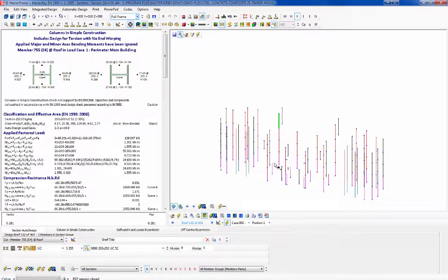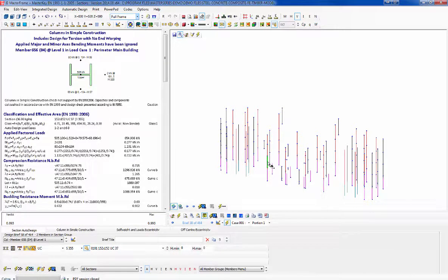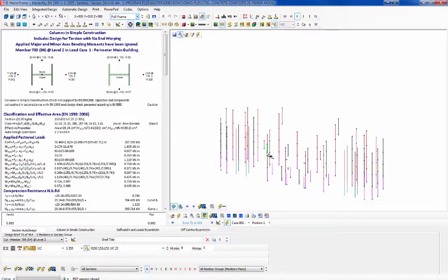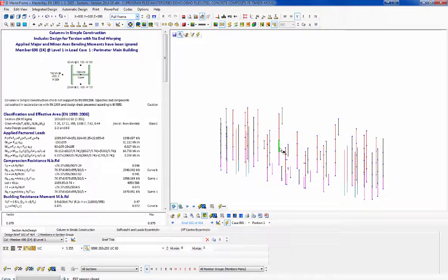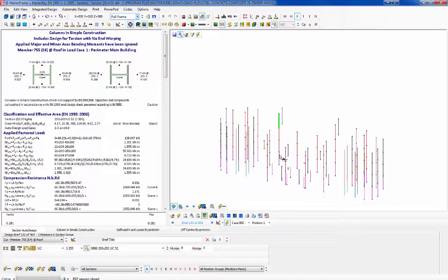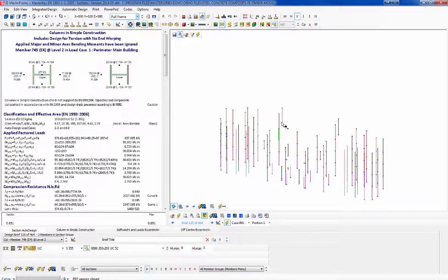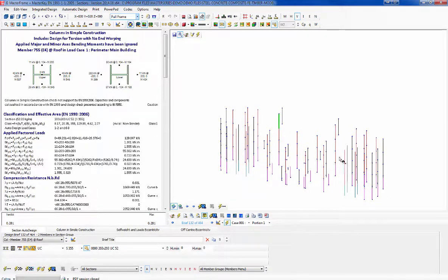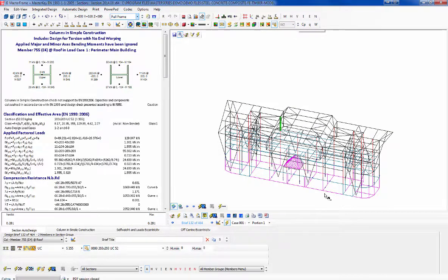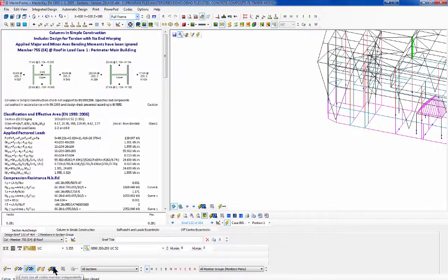And now if you look at these ones, it's a 37 and a 23, but these ones here, well, that's the concrete one, it's a 60 and a 52. So it actually found a different section size that was lighter in reality. So we can do that on the whole frame if we wanted to. So we could just turn off the vertical filter and just ask it to go and auto size all the members and then reanalyze and redesign.